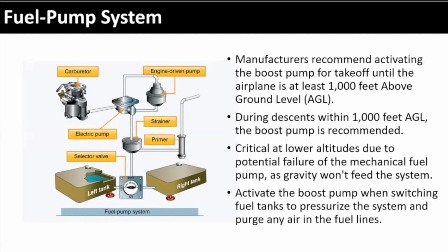On takeoff, if you are running down the runway and the engine-driven fuel pump shuts off, you're dead on the runway. So there are different times, we call them critical phases of flight: takeoffs, landings, doing maneuvers, any kind of serious maneuvers. The recommendation from the manufacturer is normally to turn on the auxiliary pump, so it's there in case something happens during that phase of flight. So during particular phases of flight, the manufacturer will recommend that you turn on the auxiliary pump instead of, or in addition to, the engine-driven pump. Okay.